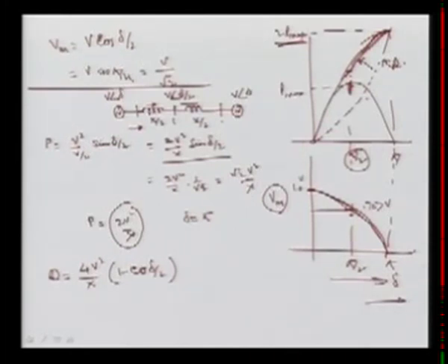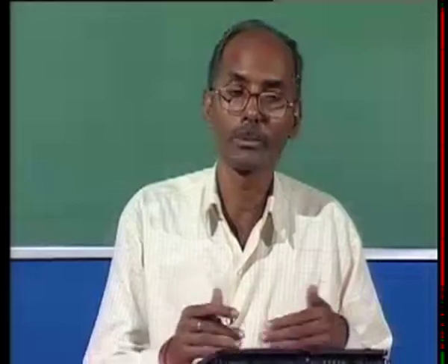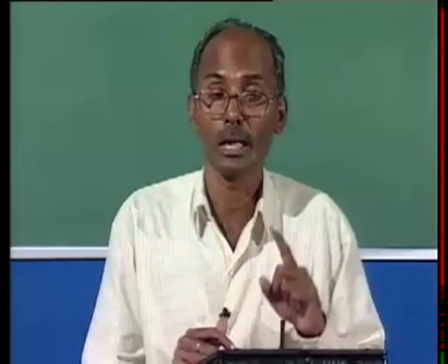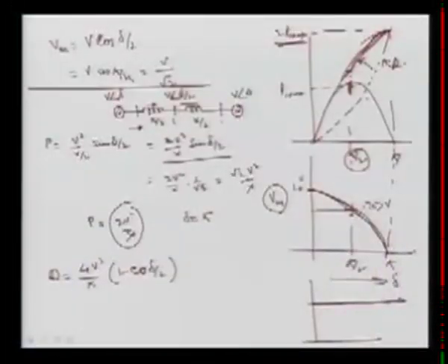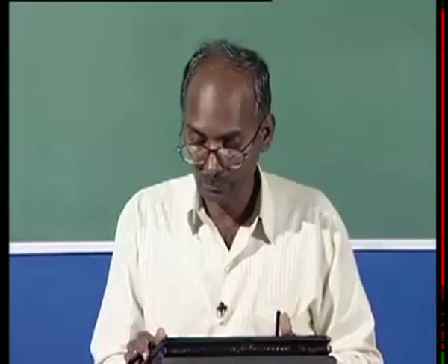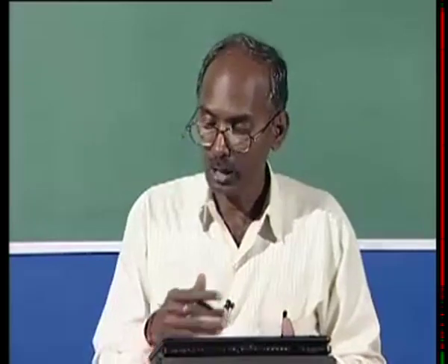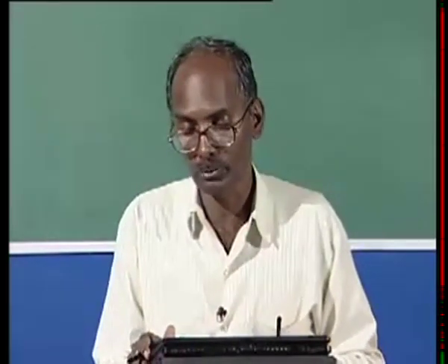So I want to tell you that by maintaining the voltage, what will the midpoint voltage be? We are maintaining it at V, constant. If you maintain the voltages in the transmission line at equal intervals, what will happen? We can transmit more power. So this is the beauty of the FACTS controller, and you can see the steady state limit is improved. Now I can again explain how voltage stability can be improved. Let us see that.